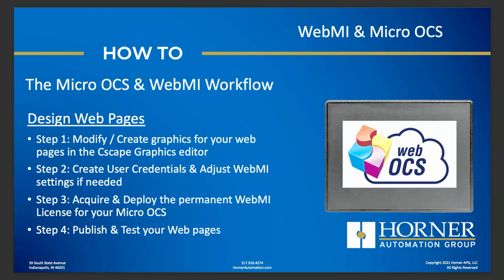Now, once you've got the web pages the way you want them, and again, it's no different than designing screens for an OCS. The process of adding graphics and adding data to the web pages is identical to creating an OCS screen. But once you've completed that process, now there's a couple more things. You need to create those username and password credentials for a variety of different personnel to be able to access the OCS using WebMI. Okay, so that's a step that needs to be taken.